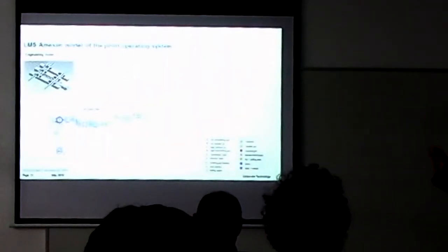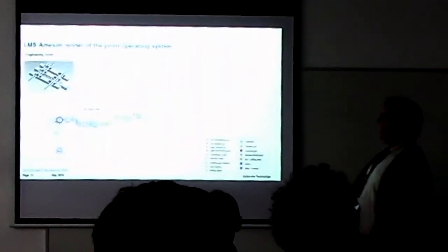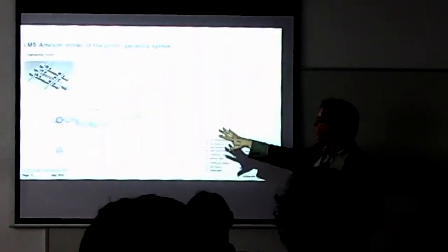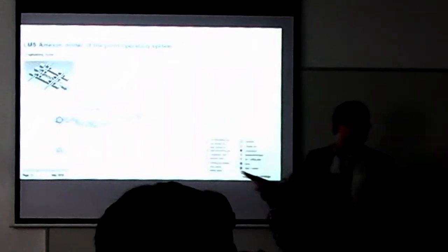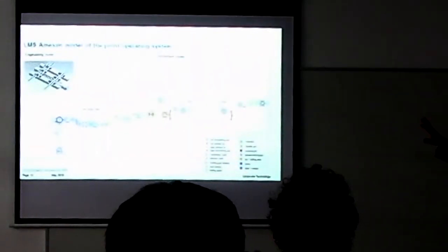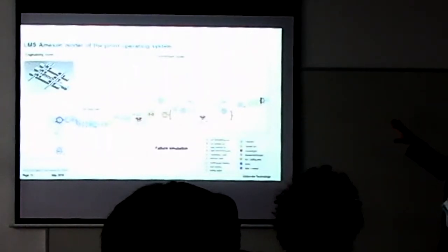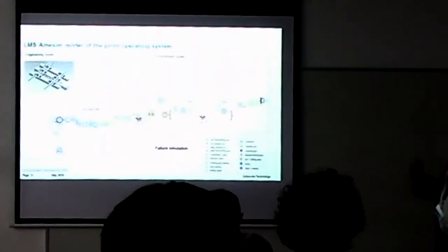So what we did there was re-engineering the system. We built an AMESim model, a mechanical model of the point machine. We also built one for the environment and introduced some failures, so we were able for the S700K to reproduce failures, compare them with real measurements, and go from there. So that's the idea, how we did it in that first slide, the old way.